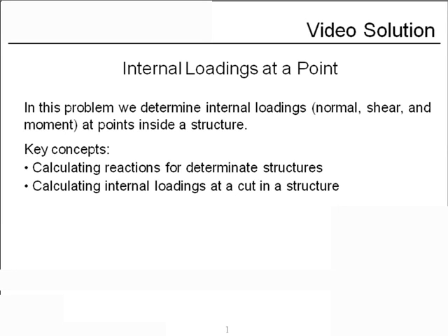An important purpose of structural analysis is to figure out internal loadings at a point in a structure. So in this problem, we're going to determine internal loadings, specifically normal, shear, and moment, at points inside a beam. The key concepts we're going to work on are calculating reactions for determinate structures and calculating internal loadings at a cut in a structure. Let's take a look at our beam.